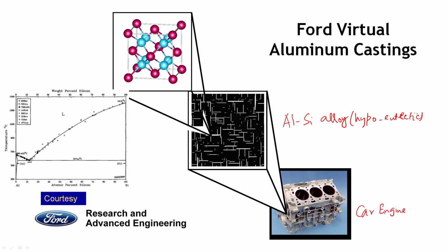And what will it have? It will have aluminum, we will show some microstructure now, and silicon needles. It can also have a little bit of copper. Then you can have precipitates like what you have seen in case of planes. So now you can actually go from casting to the microstructure to the atomic level.